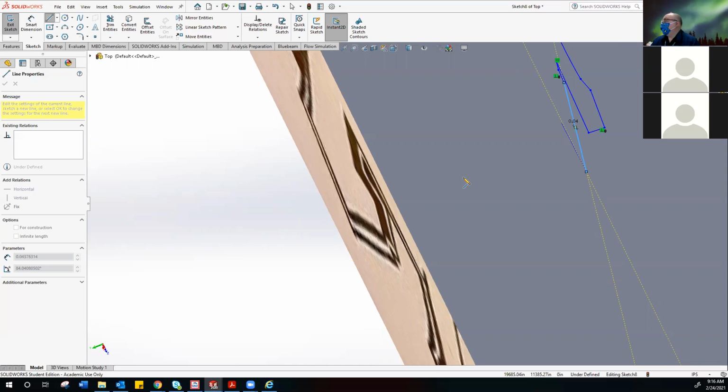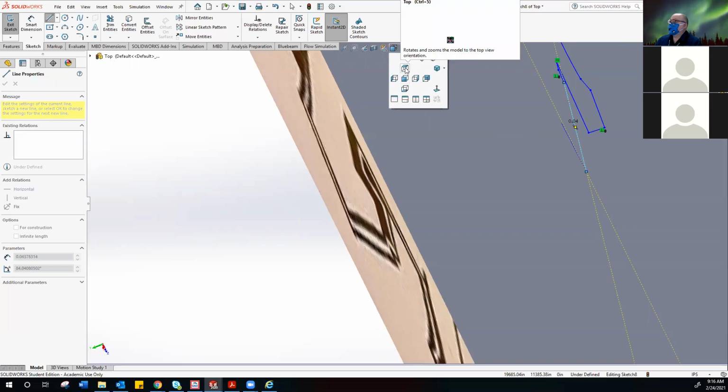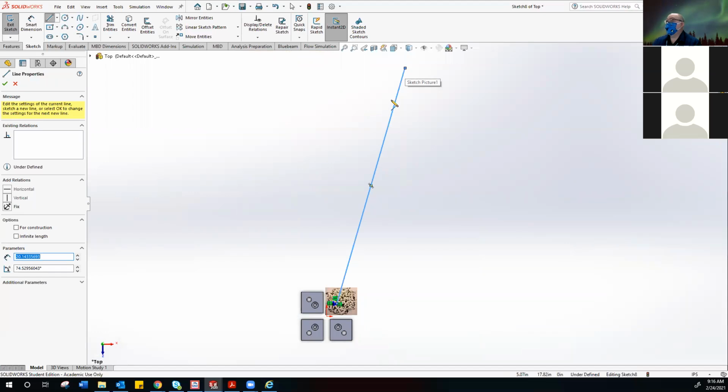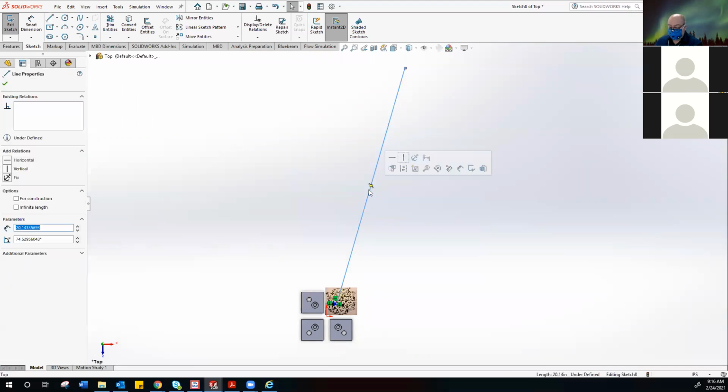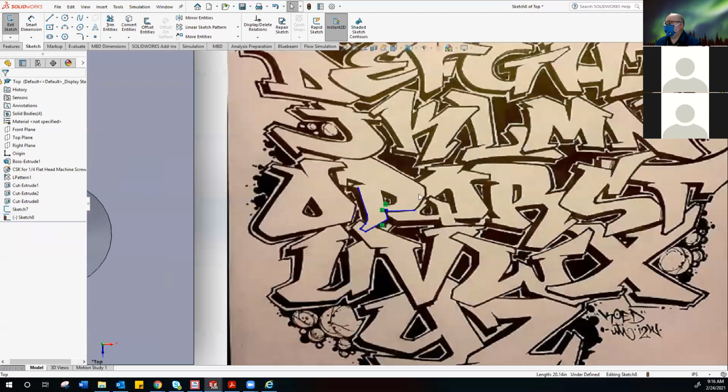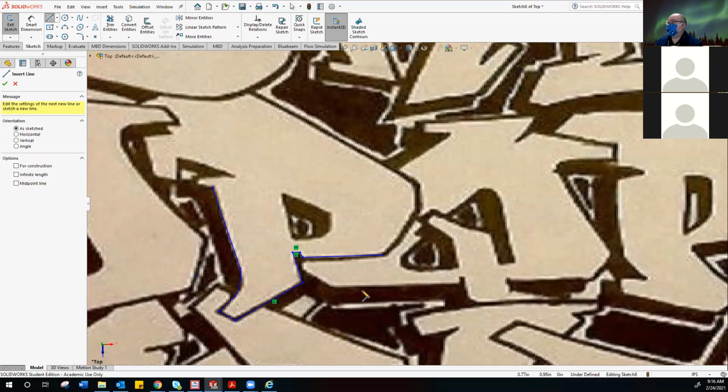Well, I just messed up. This is going to happen to a few of you where you can no longer see what you're doing. That's where you need to deal with your view orientation. Just go back to where you're supposed to be. You're going to have a weird line out there. And when you try and move your mouse around the wrong way by hitting that roll button, it's going to just throw a line out in space. Fortunately, this one's not too bad. I've had lines that were probably equivalent to a light year because I got startled or I wasn't paying attention. When that happens, go ahead and cancel all your line, delete the mistake, and then zoom back in on where you were left off. And then just pick up again where you left off.